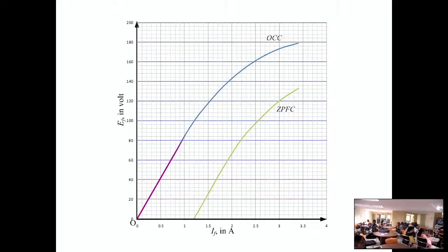So first of all, this is the air gap line and this is the VT value. See, 127 volt, that is the VT rated value per phase basis. So draw this line. So this is one corner of the Potier triangle. And now equal to this length, draw this line. So that is AD, base of the Potier triangle. So AD equal to OF dash.